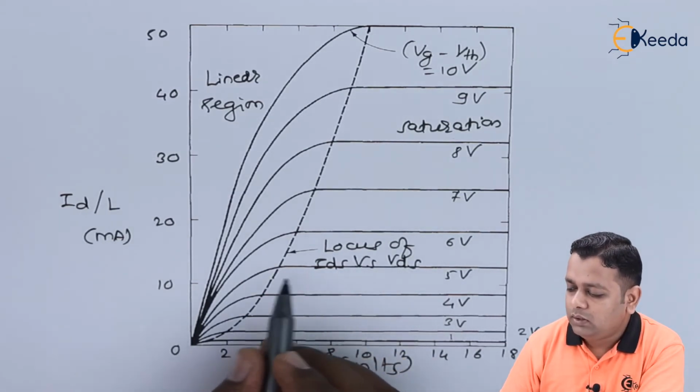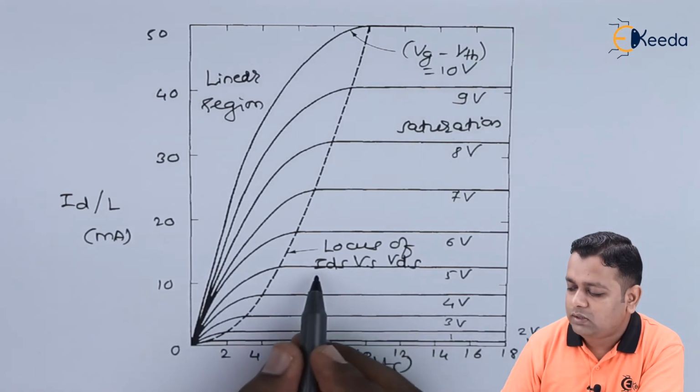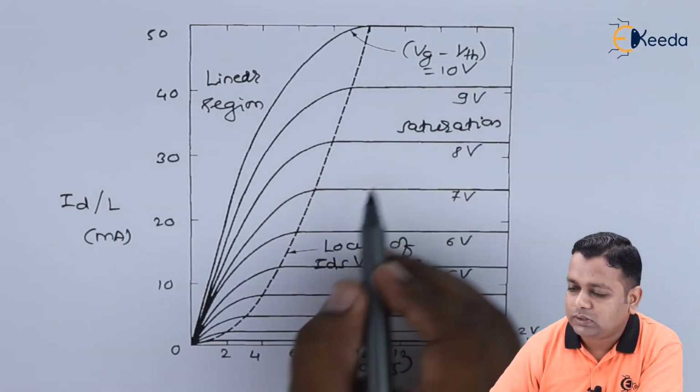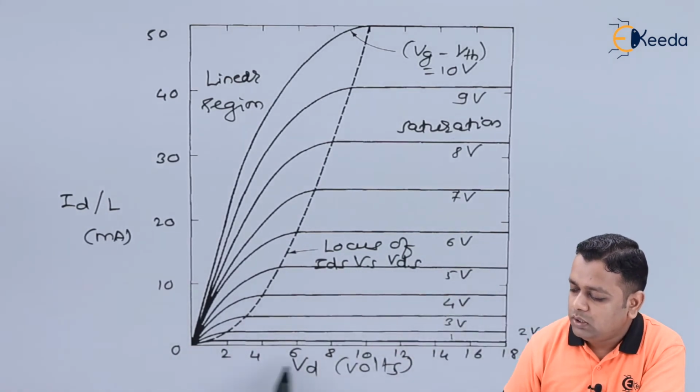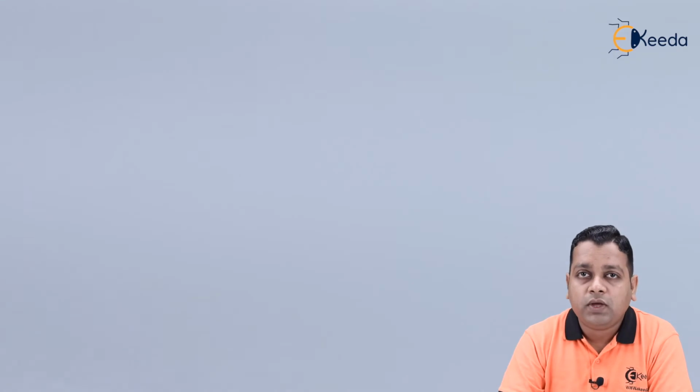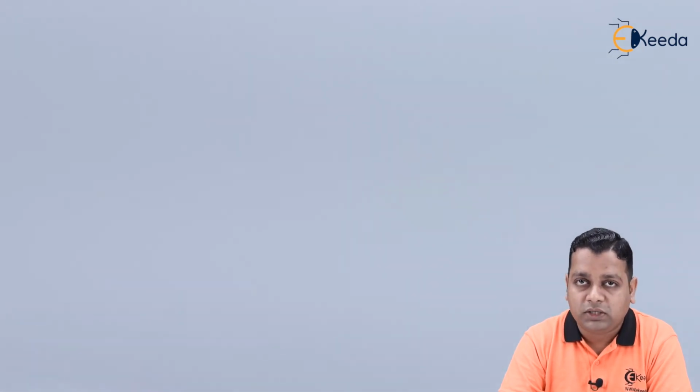So after the drain voltage and the drain current are at the saturation level, we find the constant lines with respect to the changes in the drain voltage. As we have just seen, the drain current versus the supplied drain voltage and the various constant values of the gate voltage here. Now let us have a generalized expression that expresses the output drain current.